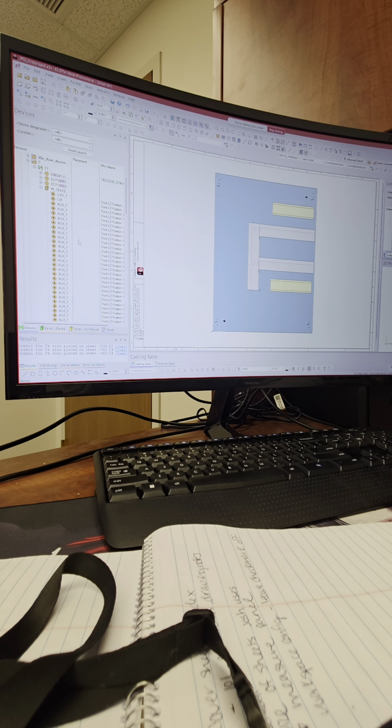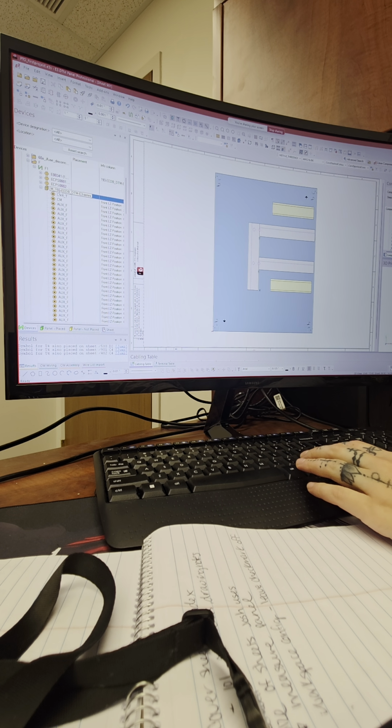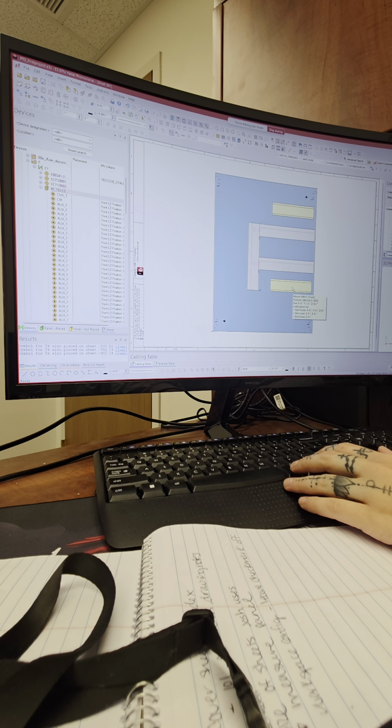So what could have happened? We can circle back to these and actually fix these parts. For right now, I just wanted you to place a couple of these extra parts so you can get some visual on your panel layout. All right, so let's just put that on your DIN rail itself. I think that's where it's supposed to go. Well, I'll put this on a mounting plate. Just first find out what the mounting description is for this guy. Does it even go on a DIN rail or not?